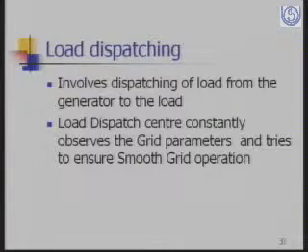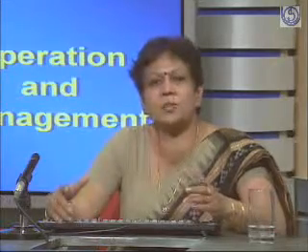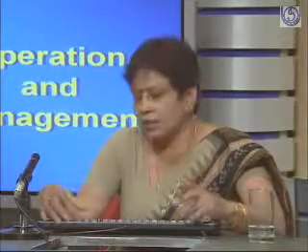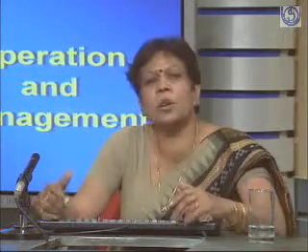So all these parameters are available in real time at the load dispatch center because you have data coming in from all the substations within the region. And whenever, like explained, there is a fall in load or an increase in load, then the generation has to be accordingly increased or decreased. And that function is carried out by the load dispatch center, that which station is to be backed off, which system has to shut down, or where load shedding is to be carried out. That also is being done by the load dispatch center.